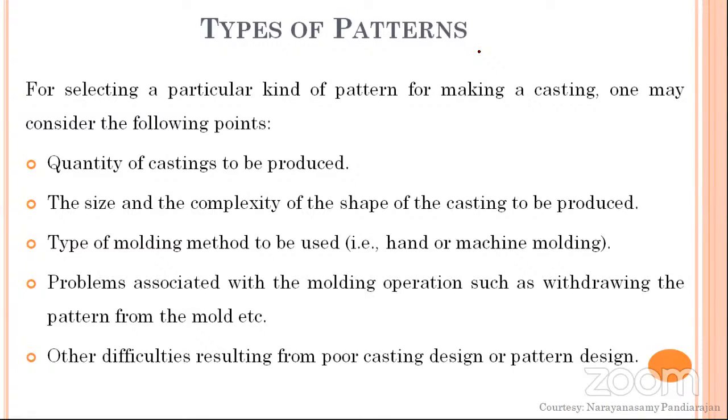And then next comes the type of molding method, whether I'm going to use hand or machine molding, whether I'm going to ram it by hand or by using a machine. Next, the problems associated with the molding operations, such as withdrawing the pattern. Now, how well you are placing your patterns inside the sand mold. The type of pattern you select also depends upon your placement.